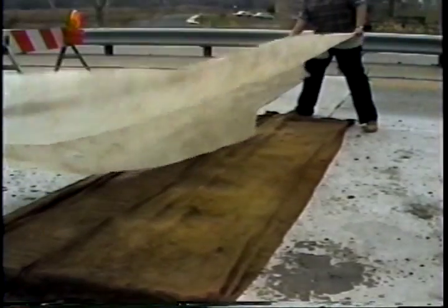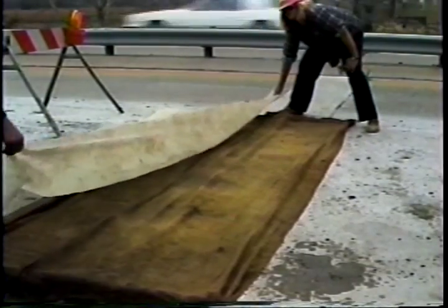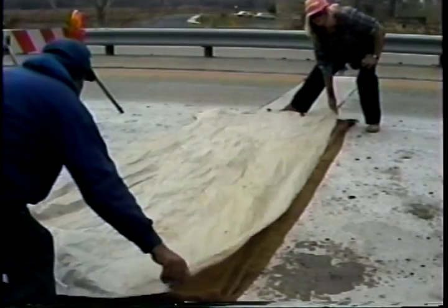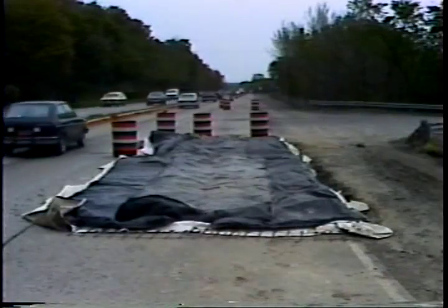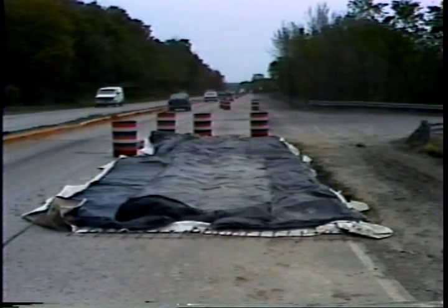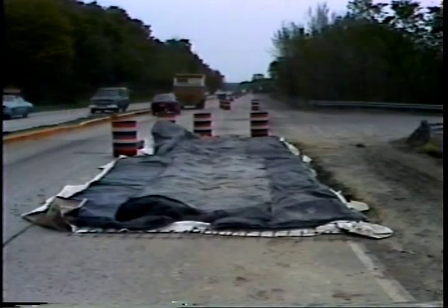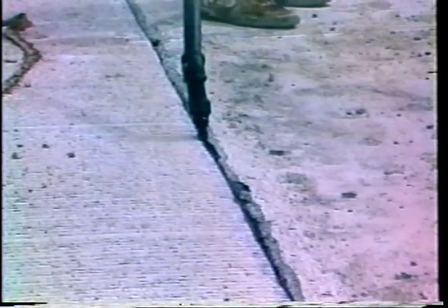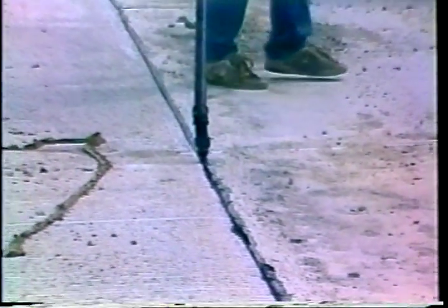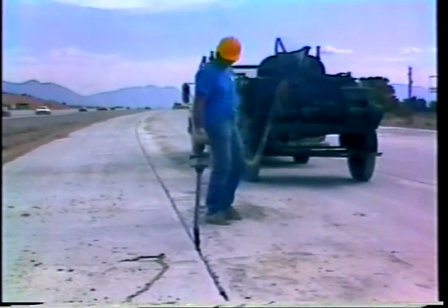Sealed curing with moist burlap and polyethylene sheeting can also be used. However, shrinkage cracking can result because of the rapid moisture loss when the seal is removed. The use of insulated blankets during cold weather can promote rapid curing and allow early opening to traffic. After the concrete has gained sufficient strength, the joints adjacent to the repairs must be resealed. Normal joint sealing procedures and materials should be used.